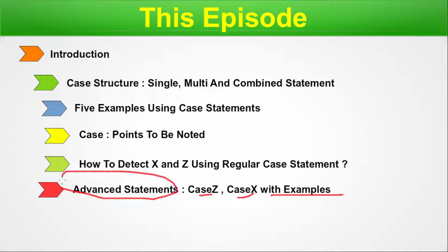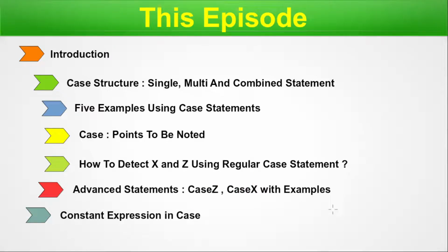These are advanced case statements in Verilog, and you will see this is a basic fundamental difference from any programming language, because in any other programming language you will find case or switch case, but you will not find this kind of specific case Z or case X. These are very much specific to Verilog, so you must have a good knowledge about them and using them. That's why we are giving examples so that you can understand it and write the code with case Z and case X.